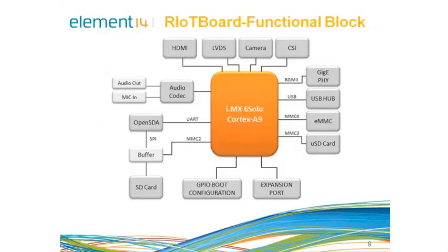Now let us have a look at the functional block of the RIoTboard. As we can see, it has plenty of interfaces available. This RIoTboard is an evaluation platform featuring the most powerful i.MX6 Solo, a multimedia application processor with ARM Cortex-A9 core at 1 GHz from Freescale Semiconductor.